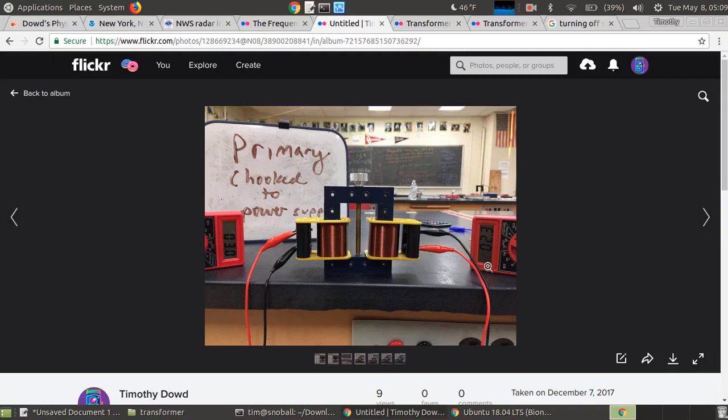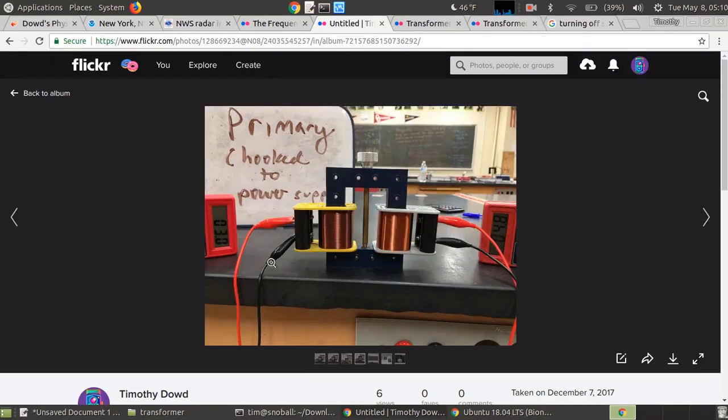We lose a little bit because the transfer is not 100% efficient here. We still have a primary voltage of 3 here, but we have 800 turns or twice as much over here. So if you solve that transformer equation, you should get twice as much voltage, or 6. You can see we're roughly in that ballpark. Again, there are some losses.